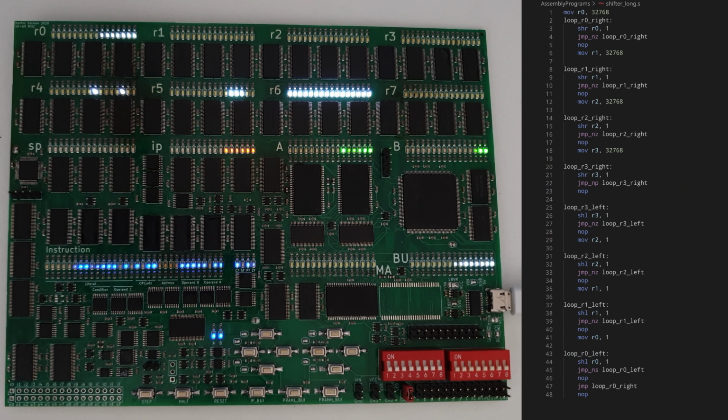Enough with the LEDs, let's move on to something that my last computer couldn't do. One really cool thing is that we have a USB to 8-bit parallel port converter on board, which just shows up as a normal serial port when you plug it into the computer, and we can interface with this serial port in code. So let's create a simple serial echo program.